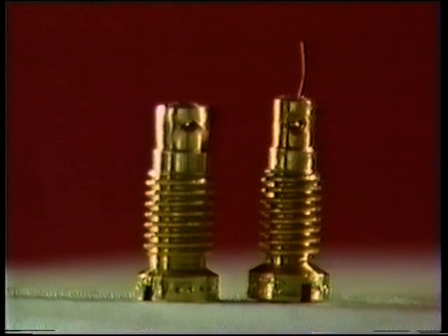What are the symptoms? If the engine runs well at idle and top no load, but hesitates or stumbles at light load, the pilot jet orifice or a transitional hole may be partially blocked. If the engine will not idle at all, the orifice may be completely blocked. The solution, of course, is to remove the offending debris.